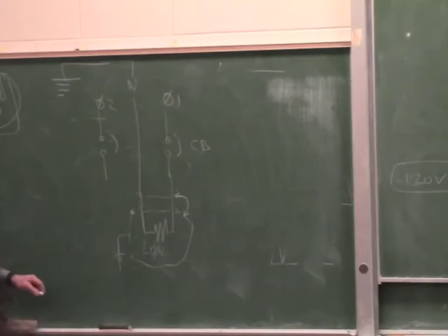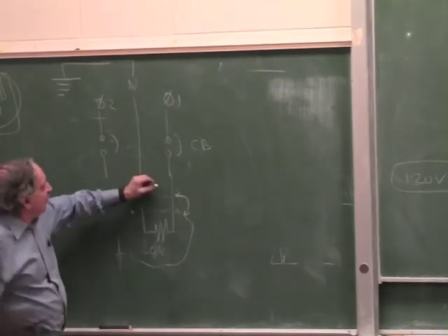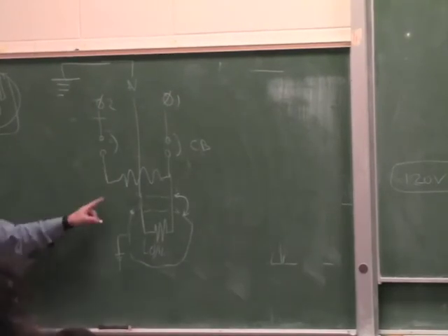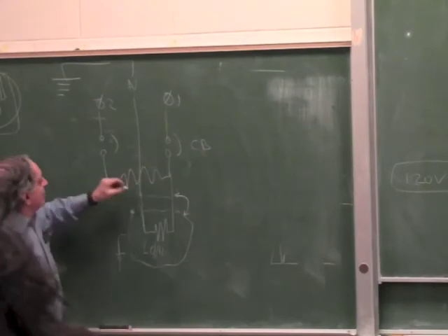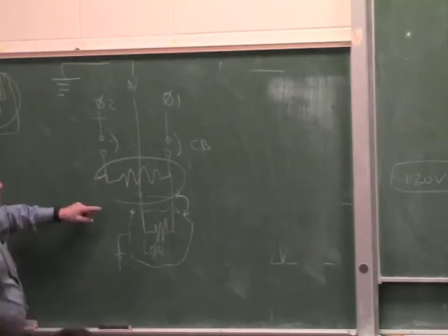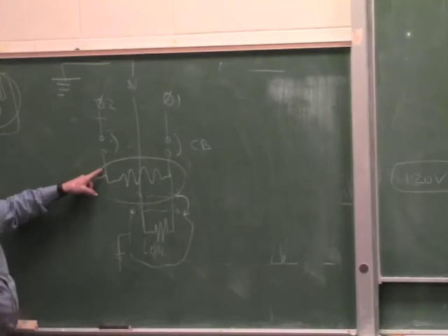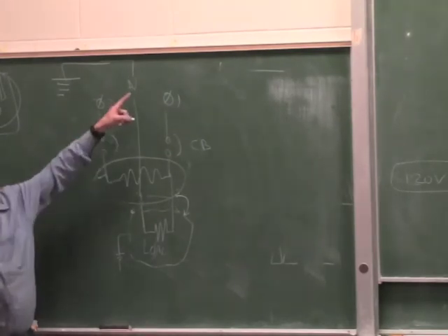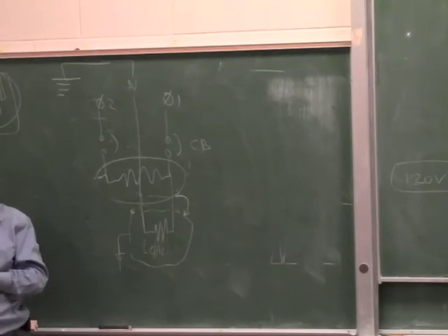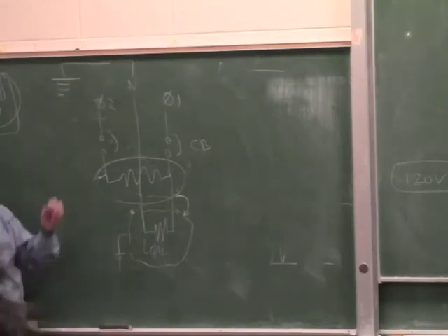Okay? So, let's say you have a thing which works on two phases, like an oven or a dryer. It will still work. Although it doesn't use a neutral, if the case of a dryer touches live, it will still be like shorting the ground to live, and the ground is the same as neutral, so it will still be shorting the ground to neutral and blow the breaker. So you don't even need the neutral wire for this system to work, but the neutral has to be grounded outside the house.